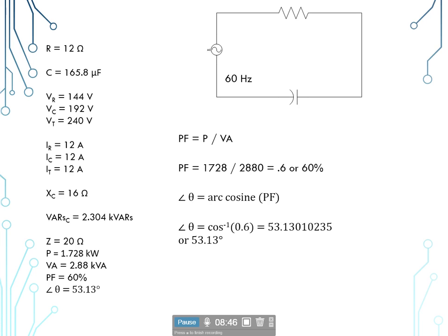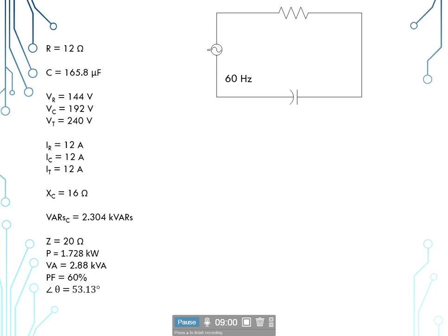The power factor can be a percentage because it is a ratio. A ratio is a percentage, right? So it's a ratio of the true power to the apparent power. Now we have all our different calculations for our expected values that we can use as a base for our live readings that we'd go out and make on the circuit.